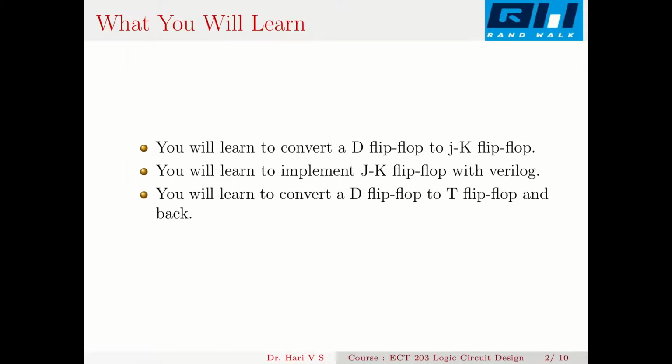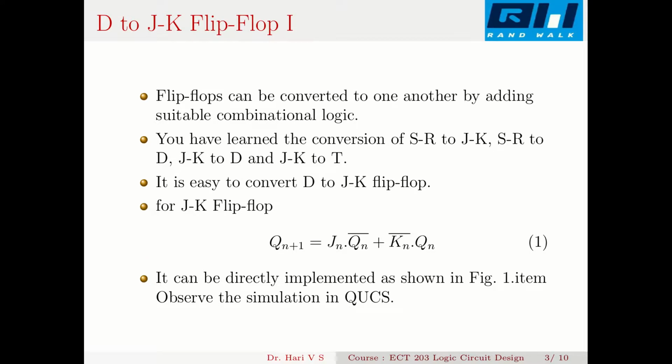So what you will learn in this video is you will learn to convert a D flip-flop to a JK flip-flop. Then you will learn to implement a JK flip-flop with Verilog, that is an edge triggered flip-flop. Then you will learn to convert a D flip-flop to a T flip-flop and back. So first let us consider the conversion of a D flip-flop to a JK flip-flop.